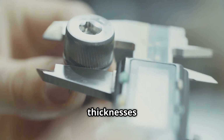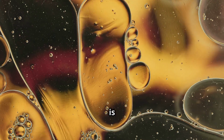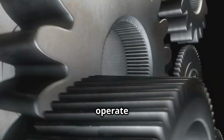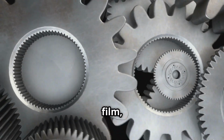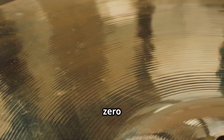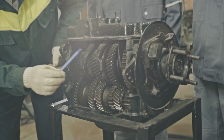The oil film thicknesses are often in the order of 1 micron, which is very, very thin. However, EHL is considered to operate on a full fluid or oil film with surface asperity heights in the order of 0.4 to 0.8 microns.